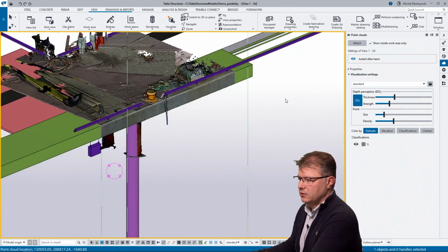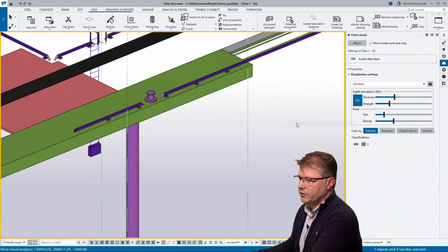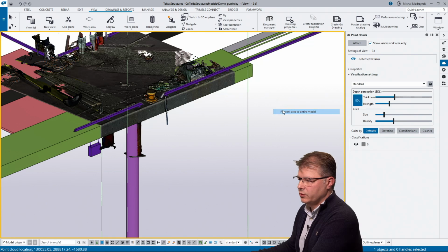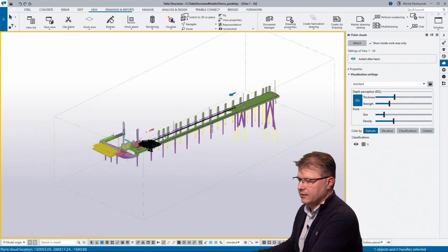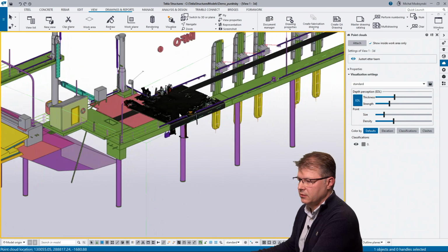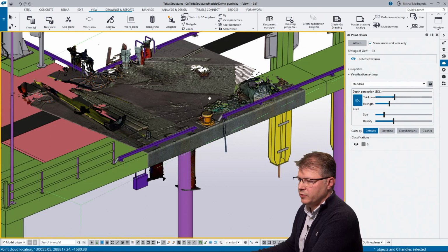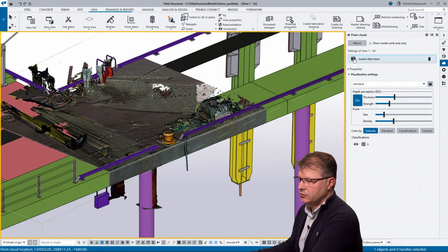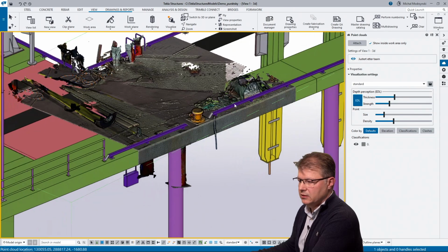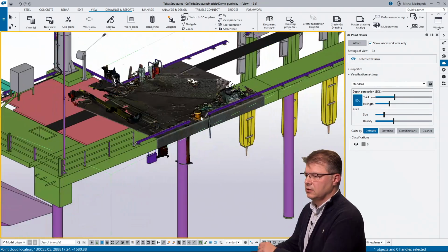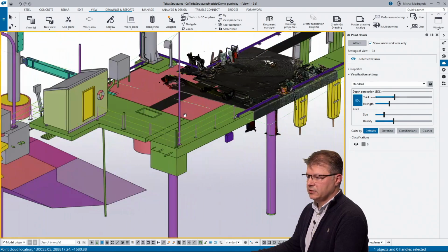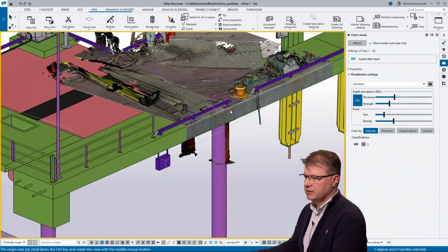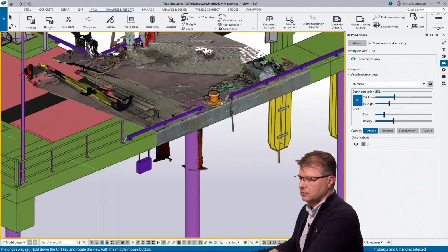When it's done, you can just click on redraw view or fit work area to entire model, and Tekla will remember how you cut the point cloud until you turn the point cloud off and on again. This way it's much smaller, much lighter, and easy to rotate, zoom and pan in Tekla.